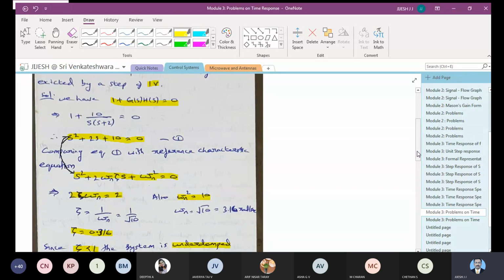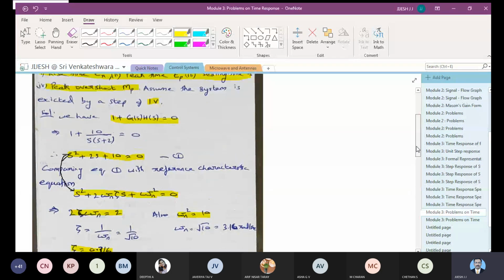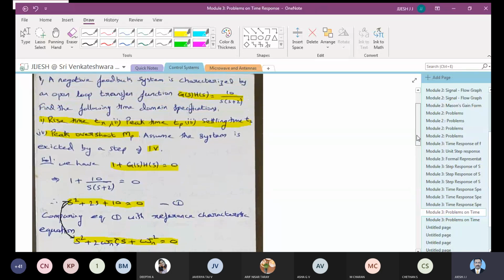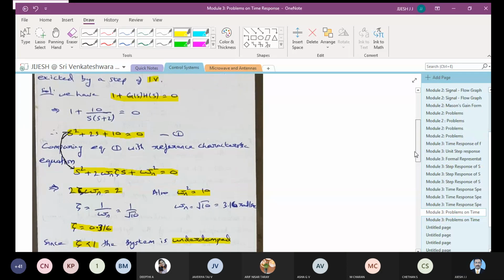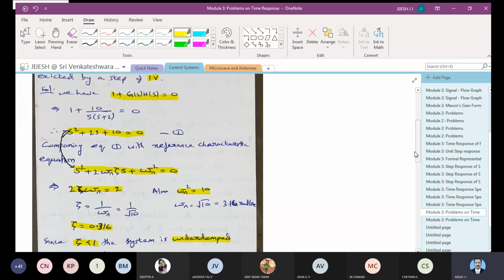So I have also written all the equations for phi and everything. You can use those things and find out phi, substitute it and simplify it. What is the equation for phi? Refer to the previous class and let me know what the equation for phi is. Any one of you? Tan inverse of under root 1 minus zeta square by zeta. Yeah, that is correct. You use that equation, find out phi, substitute all the values and simplify, and finally you tell me what that answer is.